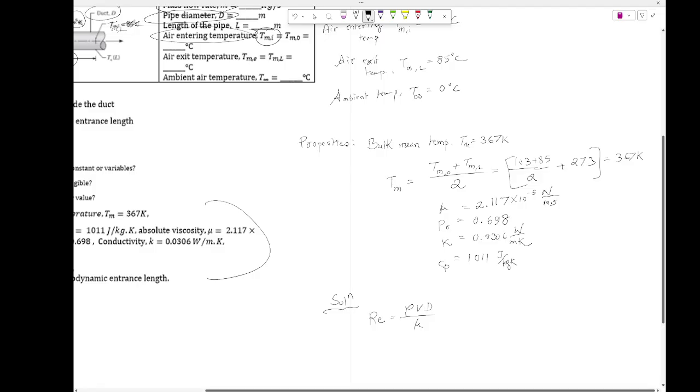And that's where the fluid mechanics come again here, because this class has fluid mechanics as a prerequisite. If you'd like to understand convection, you need to know fluid mechanics. Not all the ins and outs, but you need to know the mass flow rate equation. What is the mass flow rate equation? M dot equal to, anybody remember? Rho density, A cross section, V velocity. So M dot equal to rho A V.